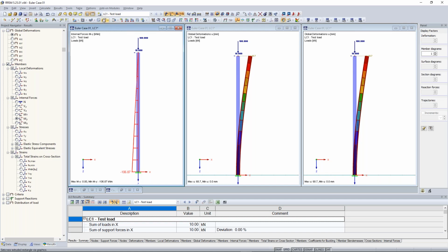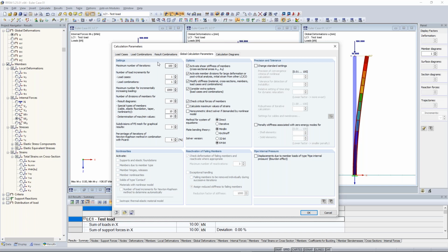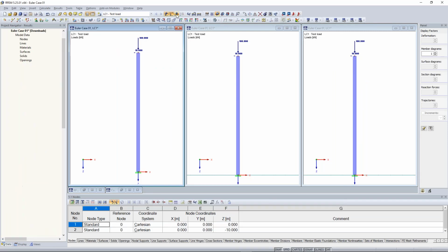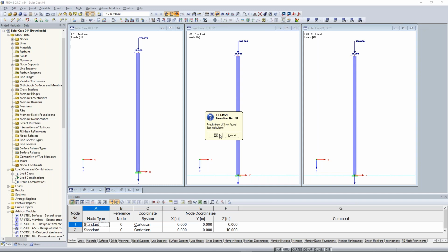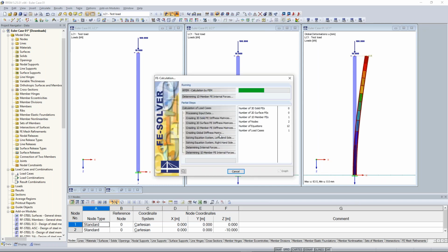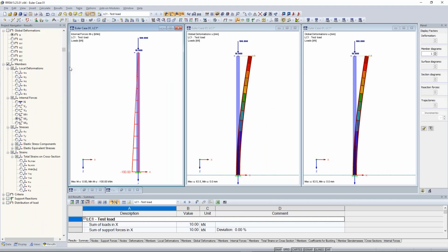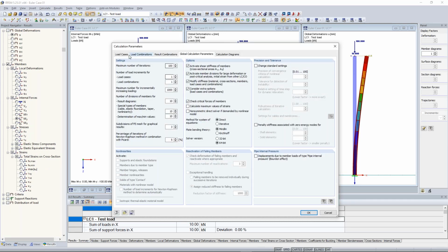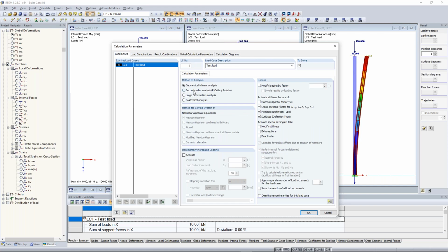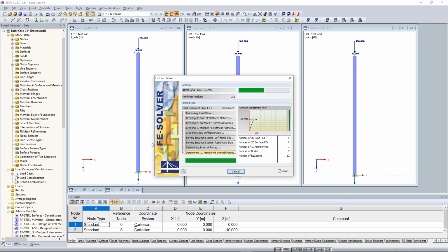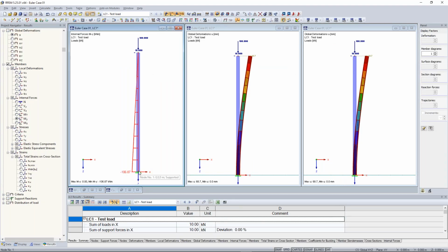I will show you the internal forces again at the analysis of a geometrically linear analysis, so theory first order. Here 100 kilonewton meters. Now again with theory second order. And now we get an additional 6 kilonewton meters. Where does it come from?